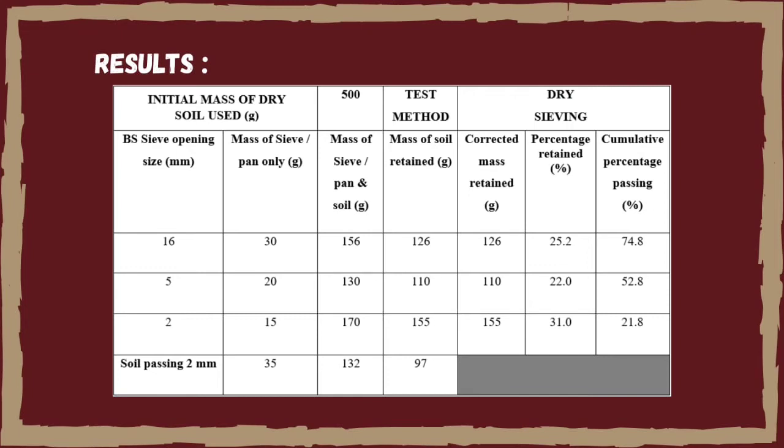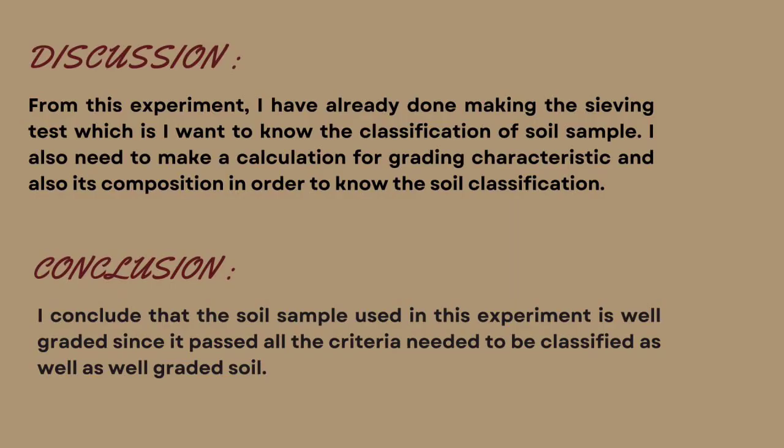So this is the result. Next is the discussion. From this experiment, I have already done the sieving test, because I want to know the classification of the soil sample. I also need to make a calculation for grading characteristics and also its composition in order to know the soil classification. I conclude that the soil sample used in this experiment is well graded since it passed all the criteria needed to be classified as well graded soil.